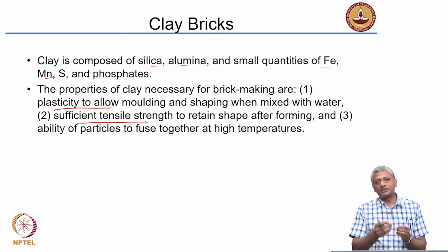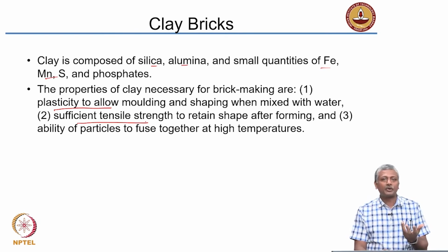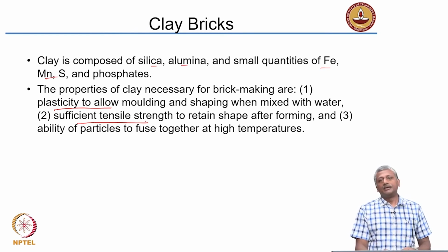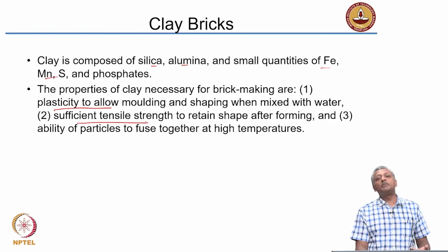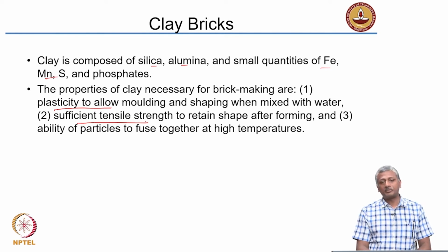If this water dries out too fast, it may lead to desiccation, or drying, cracking of the clay. Now you don't want that to happen obviously, even before you form the brick. So the tensile strength should be capable of resisting any cracking tendencies of the brick. Okay. And finally, after the brick shape has been formed and you have dried the brick, you then need to subject it to a very high temperature firing operation.